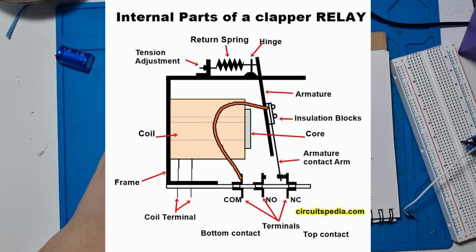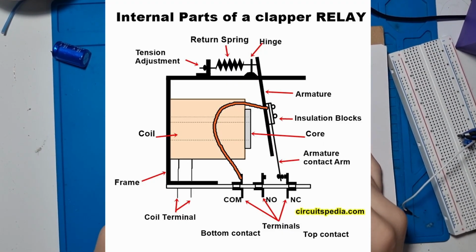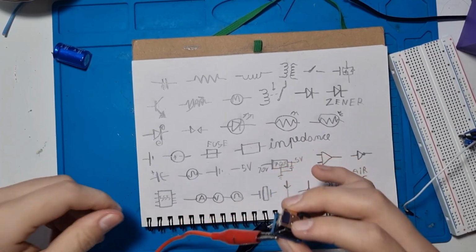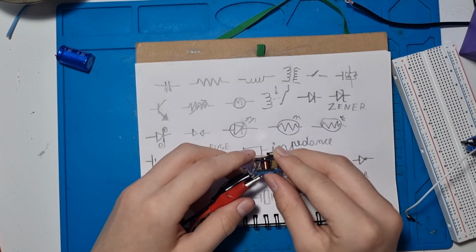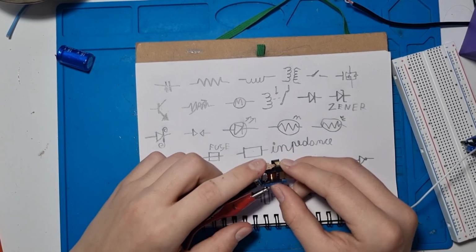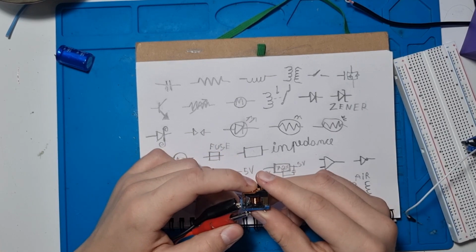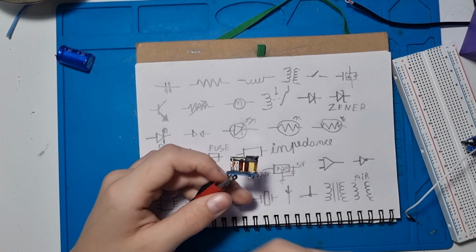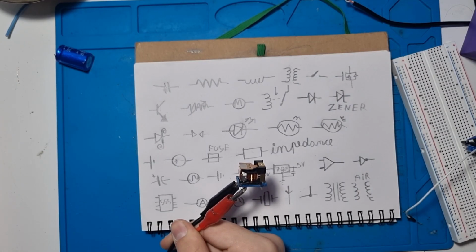We have here a relay. I have one right here, and as you can see, it has a coil, and that coil is basically an electromagnet. It's an inductor, and then it has this pin right here. You see this pin, and when I put in a voltage through it, the electromagnet takes the pin down and disconnects it from normally closed, connecting it to normally open. So it's basically a mechanical switch that you operate with an electromagnet, and you can see it clicks.